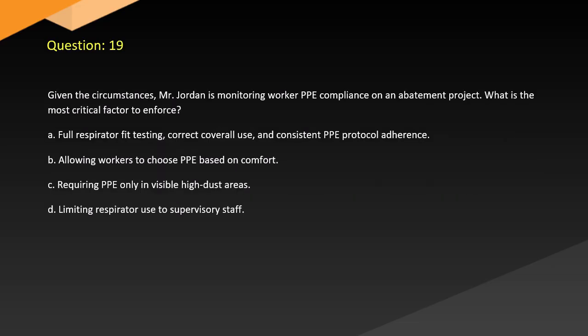Question 19. Given the circumstances, Mr. Jordan is monitoring worker PPE compliance on an abatement project. What is the most critical factor to enforce? A. Full respirator fit testing, correct coverall use, and consistent PPE protocol adherence. B. Allowing workers to choose PPE based on comfort. C. Requiring PPE early in visible high dust areas. D. Limiting respirator use to supervisory staff.